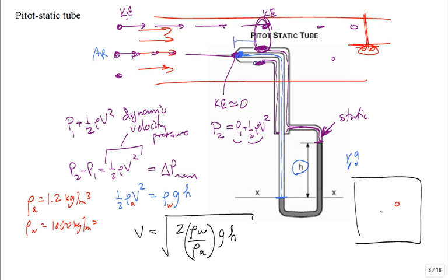What about where you place it within the sampling? What we'll do is ASHRAE and other organizations will say, how accurate do you want? And a lot of people say, I just want to get a ballpark. Well, they'll put it right in the middle, and they'll call that the average speed over the whole area. But they have all sorts of recommendations. They'll tell you what distance to put it and what pattern to put it in to get a better number for the average. Because this one in the middle will have a higher flow than this one near the corner. And if you had more of an oval shape, they have a pattern for that.